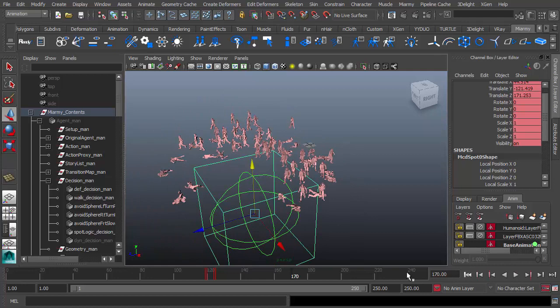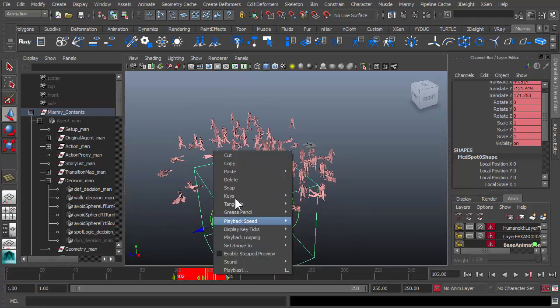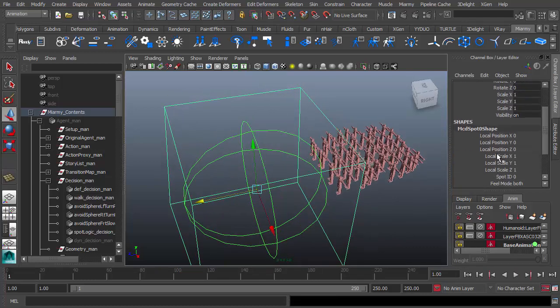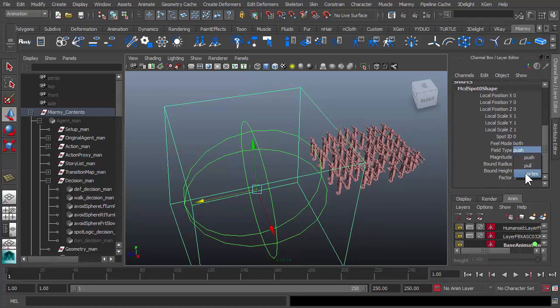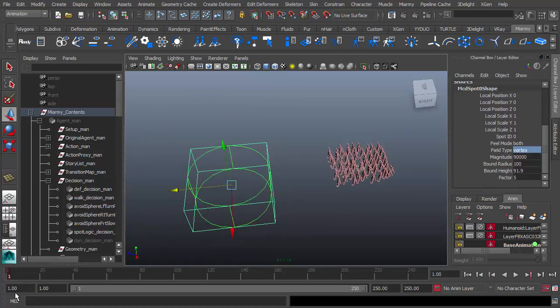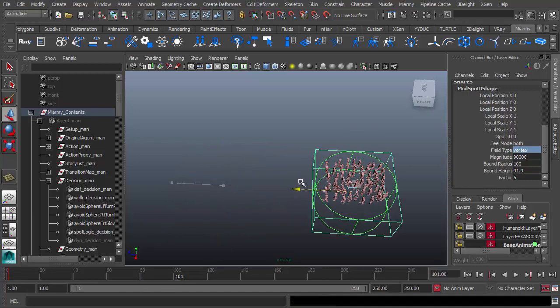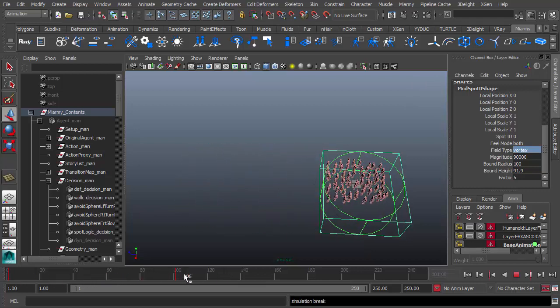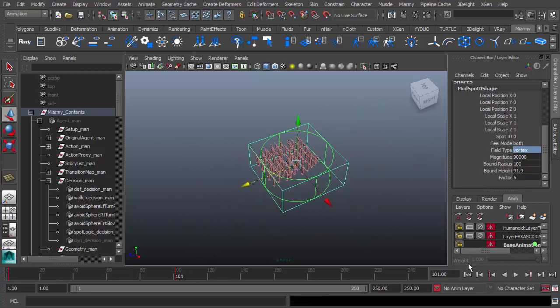You can also keyframe this for other locations for simulating multiple bombs as you wish. And let's just delete the key here and simulate a tornado. Let's first select the spot and change from the push to the vortex, and make some keyframes here, S, and this first frame to, for example, 100 frames, and let's move right here just like this, and let's run a simulation.